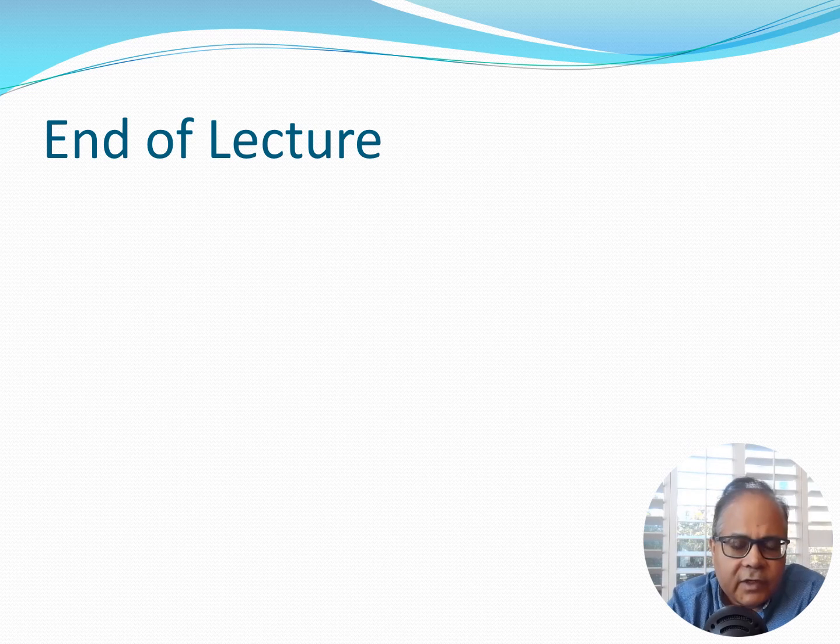So this was the video for today. It is an important topic, and we have some idea about why the demarcation at Mach number 0.3 takes place. Very often in textbooks, this is just given as a fact you need to accept, but now you see that it is actually an assumption, but it is a pretty good one, because when you are below Mach number 0.3, there is very little change in the density of air between 2 points.